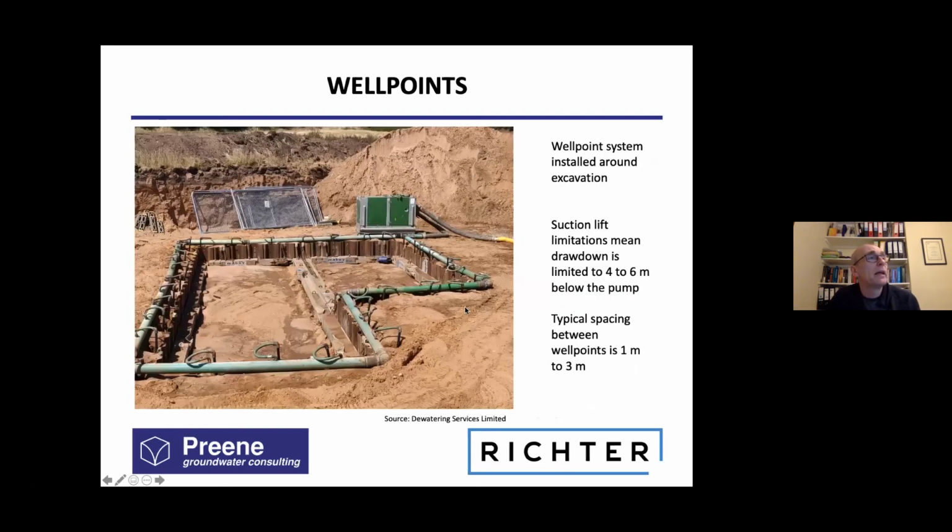This is what it looks like in practice. Here we have a small excavation, and you can see the green pipe is the header pipe being laid around the excavation, and every 2 meters or so there is a well point with this flexible connection to the pipe. The pump is over here. The pump looks like a box because it's silenced, because a key thing with most pumping systems is they pump 24 hours a day, 7 days a week. So you need to keep the noise down, particularly when you're working in urban areas. This is a silenced diesel pump. It's still quite noisy, even with all the enclosures. And if you do need to keep the noise really down, you need to go for electrical pumps, which are much quieter. This excavation isn't at full depth here. They've just dug down to place the first support frame, but here they've dewatered it inside some trench sheets, and they would excavate later.